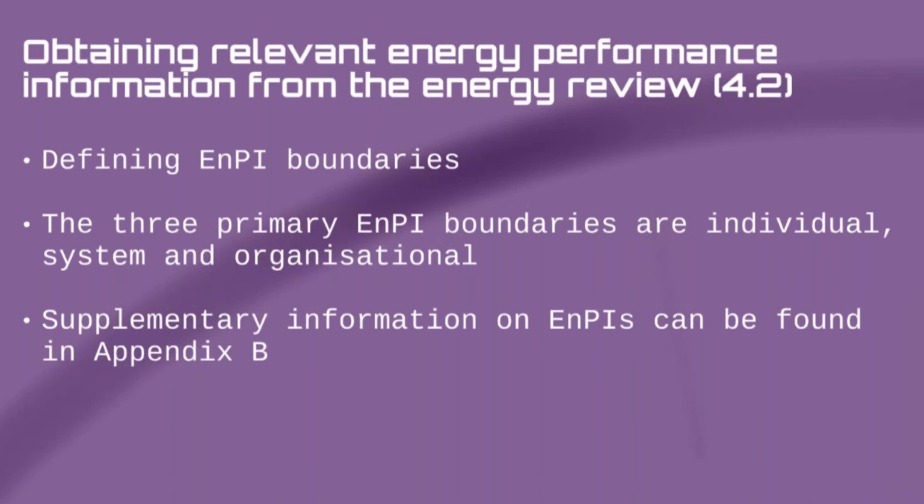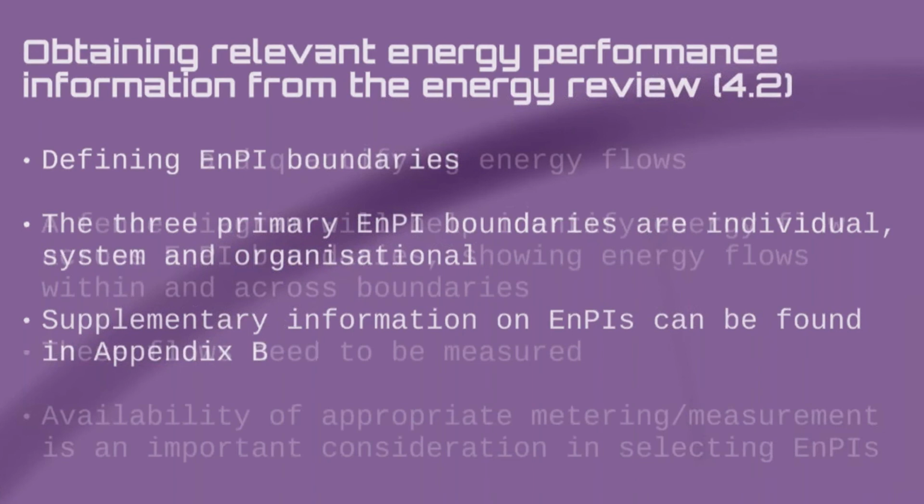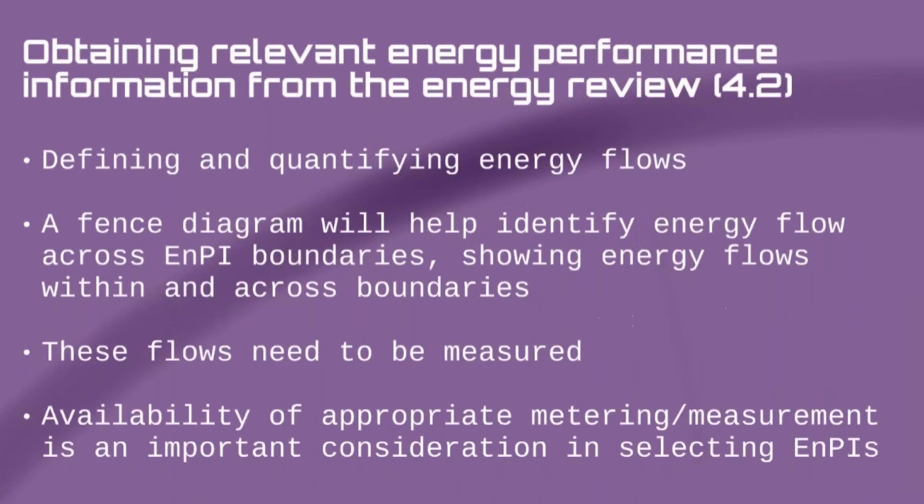And once you've established your boundaries, you're then looking at defining and quantifying energy flows. And the fence diagram will be helpful in identifying energy flow across boundaries, showing energy flows within and across boundaries. These are the flows that need to be measured, and availability of appropriate metering and measurement is an important consideration in selecting energy performance indicators.